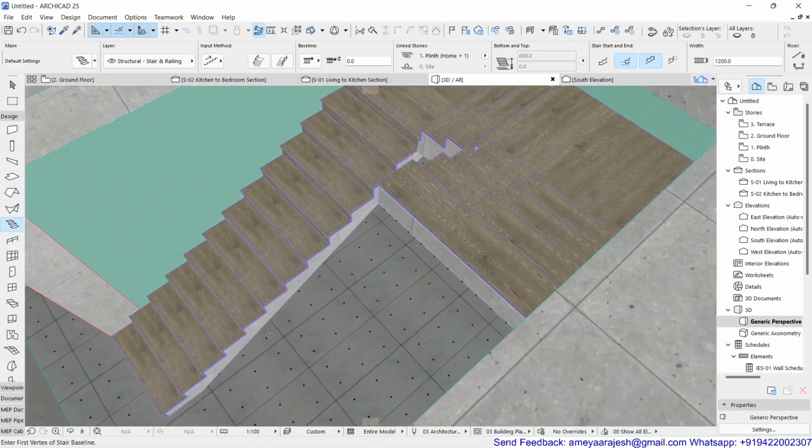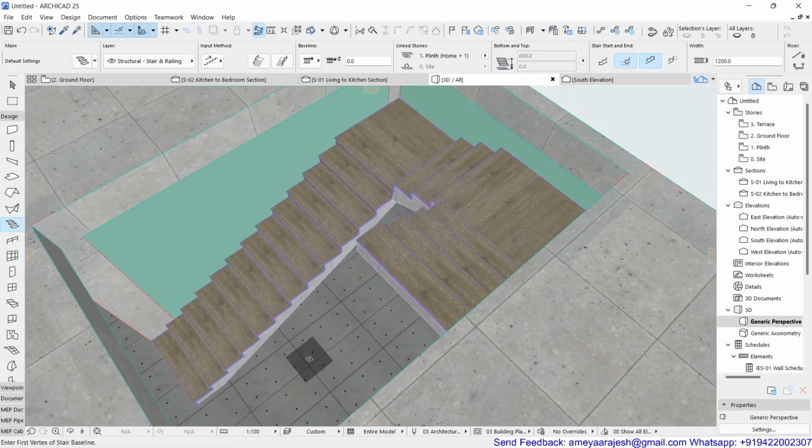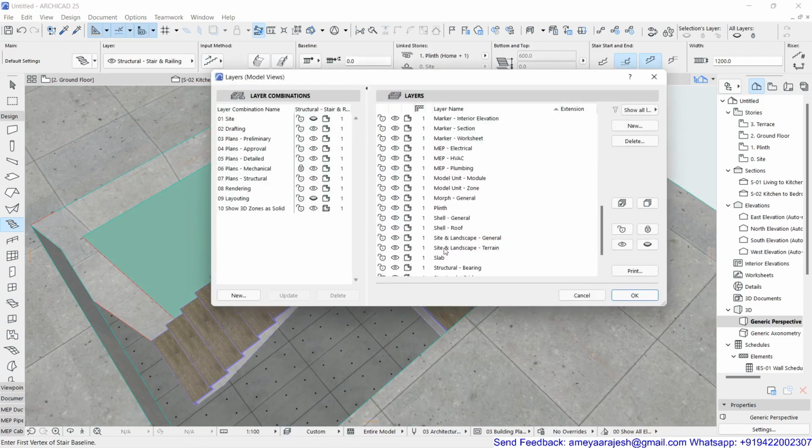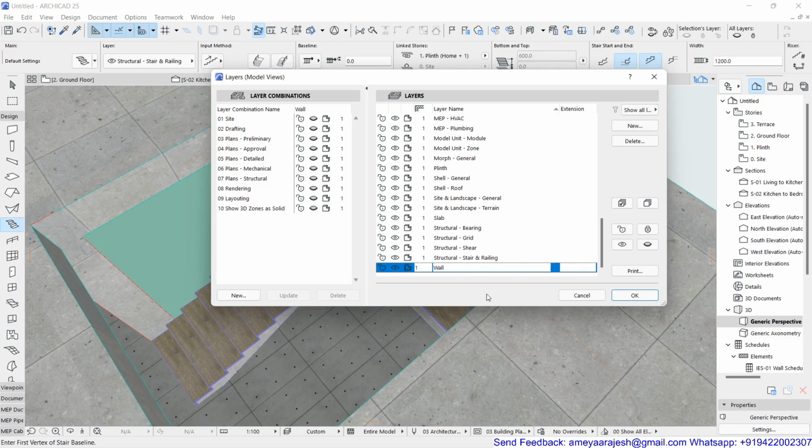You just go inside the layer, and here the wall layer which you have, we can make it transparent instead of solid. Instead of keeping it off, you can turn it off, no worries about that. But if you feel that you want to experience the wall in the wireframe mode instead of the solid, you can have this also.